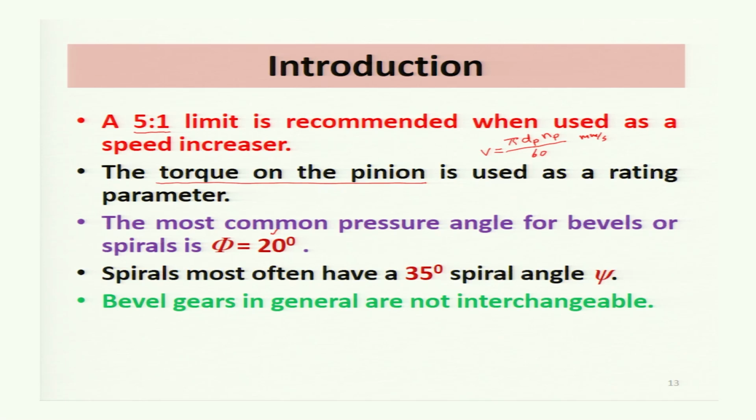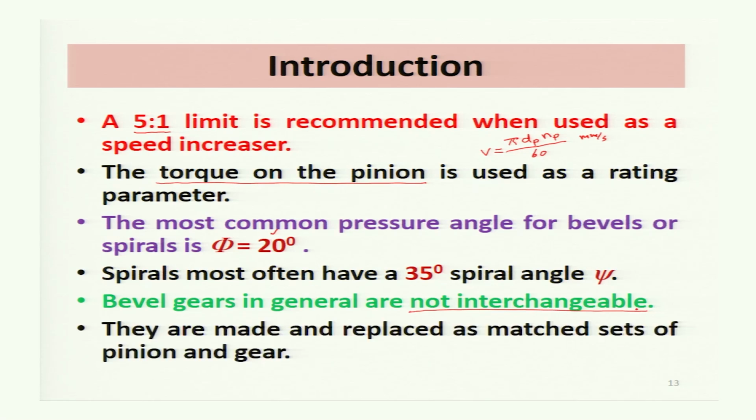Bevel gears in general are not interchangeable. They are made and replaced as matched sets of pinion and gear. So, if in a set of pinion and gear, one of the gears is damaged, then that particular gear is not replaceable. You have to replace both pinion and gear.